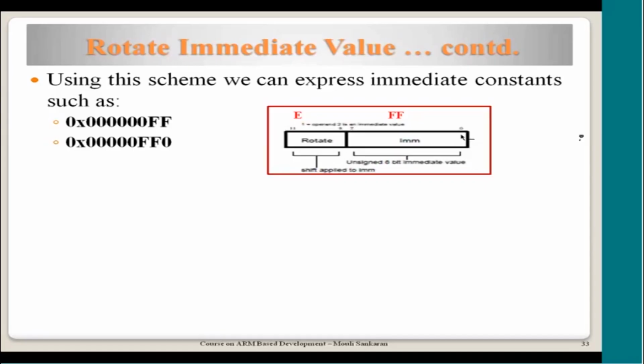This FF rotate, you remember, whatever comes out of the 32-bit will come into the MSB part of it. So this FF will pass on and then come back like this and process 28 bits. Why 28 times? Because only 4 bits are left here. So 28 times, if this FF moves, it should have come here. Please try to do it with paper, then you will understand this.